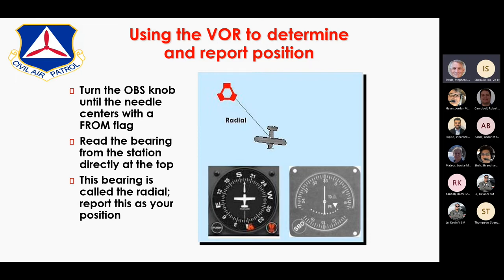If I get a particular display of information for the VOR, you play the game of, well, where am I relative to the VOR station? This would be valuable if you're flying a six-pack because of the way the needle presentation is as shown in the lower right-hand corner of this particular slide. For the G1000, this really isn't that applicable because it's a more advanced HSI presentation of the information.